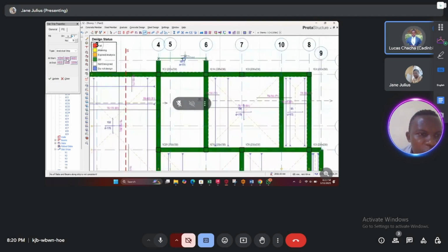So you start with option 2 for the start, and then you end at option 3 for cantilever. Yes. So now start from inside, all along outside. Now you can press control. Nice. So let's now come and detail the other slabs systematically.